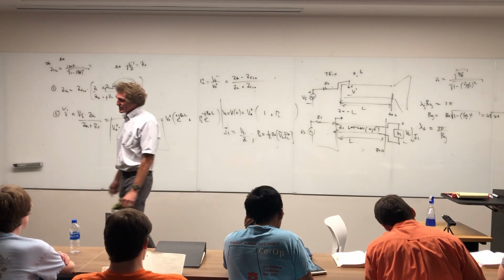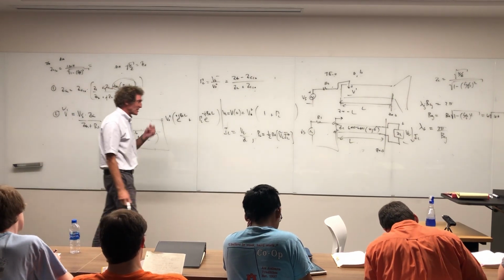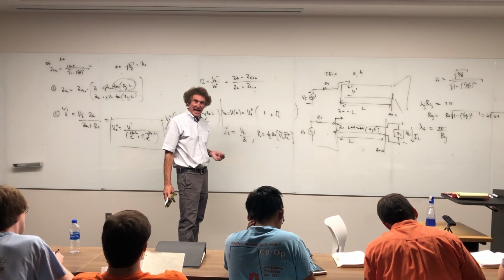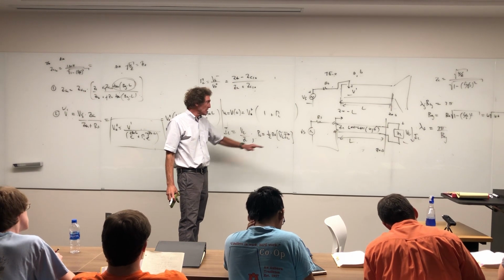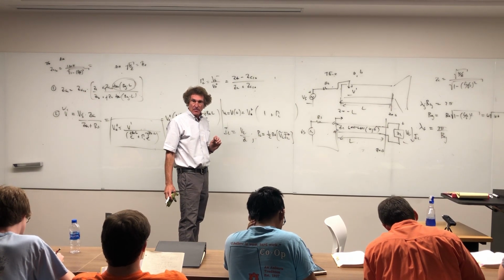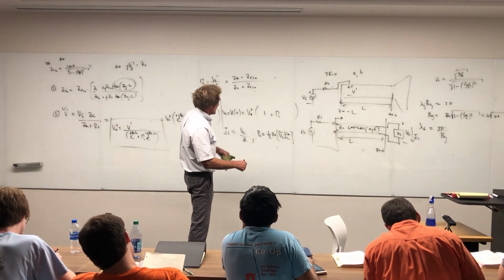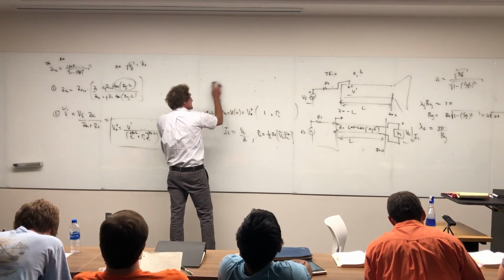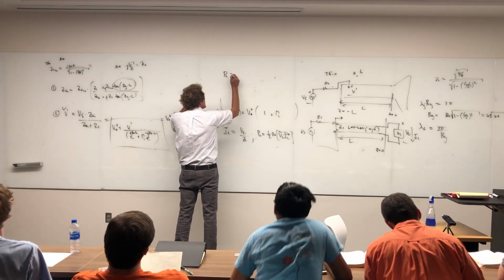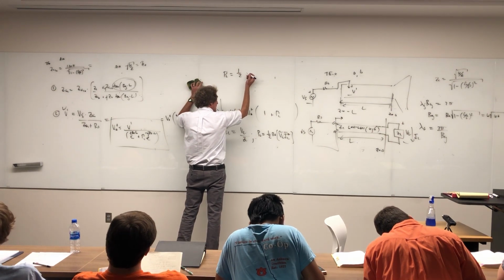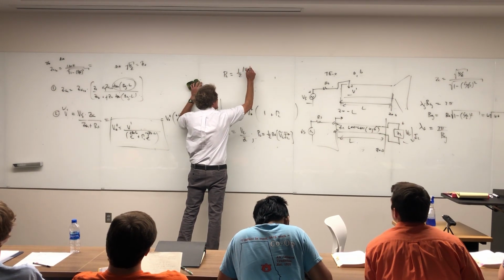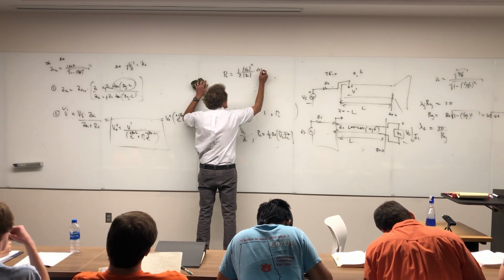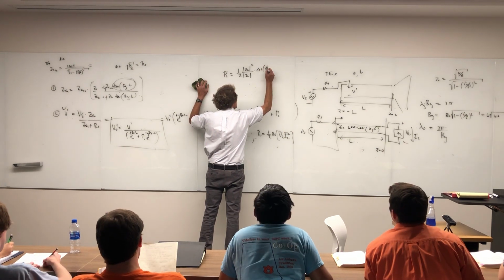What you're going to see is this is basically going to be a V squared over the magnitude of ZL times the cosine of the angle associated with ZL. But I'm going to leave it like that for now. If you want, I'll put the other one up. Another equation for this is: power at the load is equal to 1/2 times magnitude of VL squared over magnitude of ZL times cosine of the angle associated with ZL.